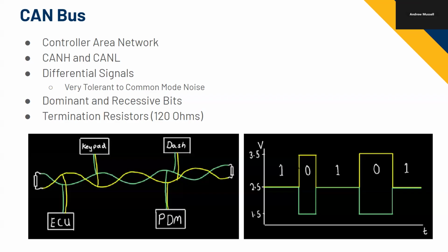And that stops reflections, which basically means, if my ECU here on the left drove the yellow line and the green line apart, and I'm driving these lines at a high enough speed, these actually stop looking like wires and we start looking at them as things called transmission lines, which you can do a bunch of reading on. It's good stuff to know for signal integrity.